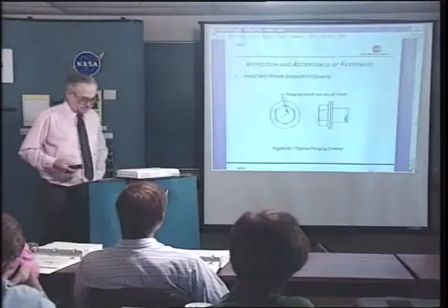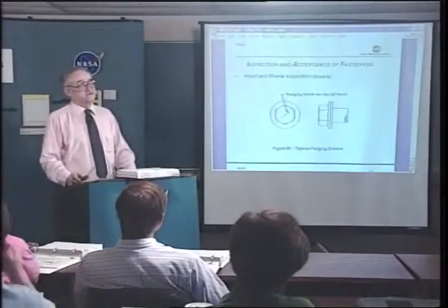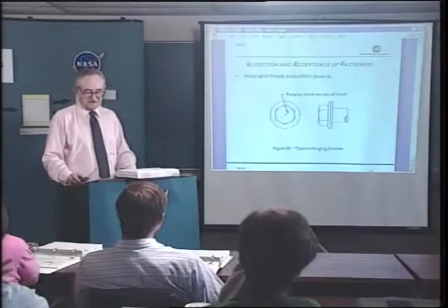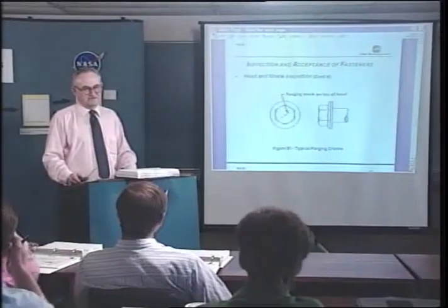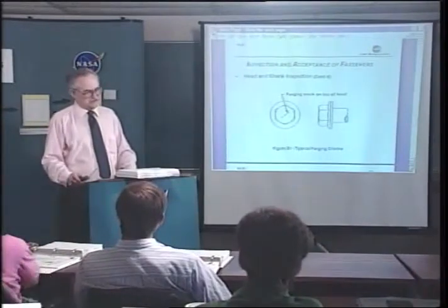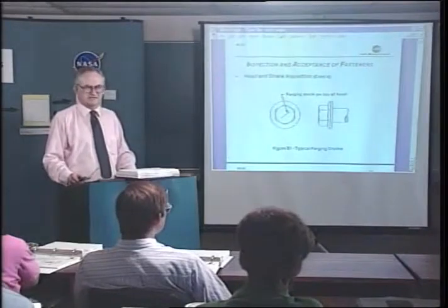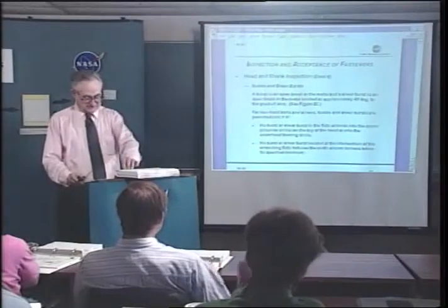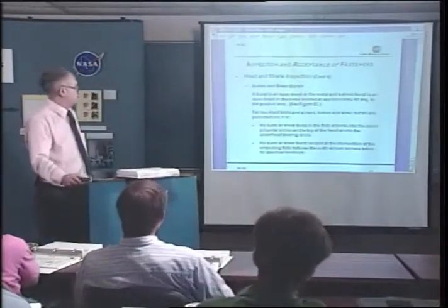And if you look at those limits on depths, you'll see that if you take 0.04 times the diameter or something like that, for a bolt that is, say, 1/4 inch in diameter, that's a pretty shallow crack. It's nothing more than a streak that you can see. So that type of crack, so-called crack, would be acceptable.